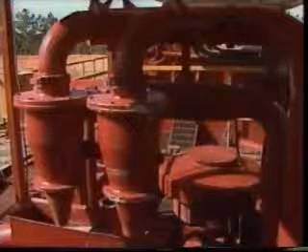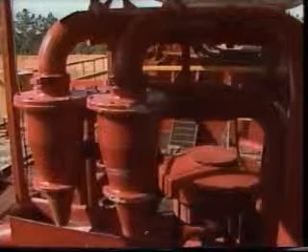Various shale shakers are available from different companies. The double-decker shaker has 2 screens mounted on a flatbed frame. A common combination of screen mesh sizes is 30 mesh screen on the upper deck and 80 mesh on the bottom. Drilled solids down to 177 microns are removed by 80 mesh screens, as opposed to 840 micron particles on a 20 mesh screen.